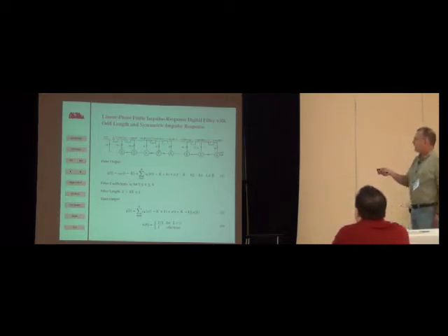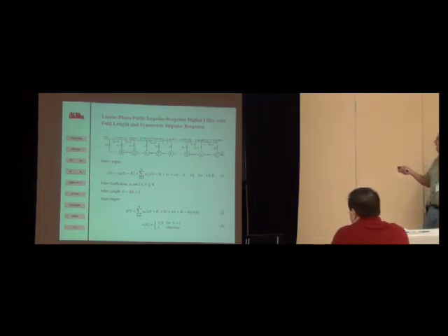Of course, the length of this filter is actually only capital K plus 1 of these coefficients. So K is sort of the half length of the filter. The total length is 2K plus 1. And I've taken equation 1 and rewritten it this way. Instead of pulling this single term C0 out, I can put it inside and sum from k equals 0 to K. I've done this just by defining this cap function.